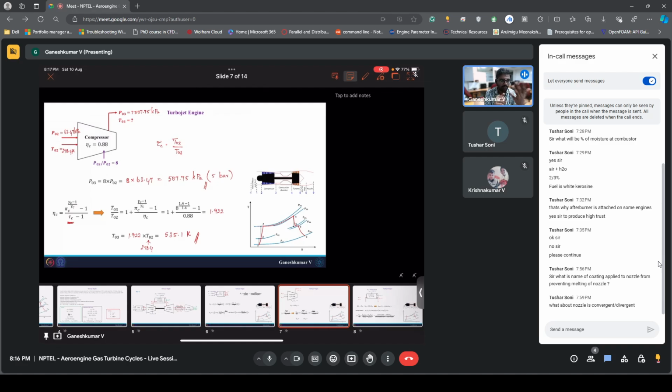But you will learn more reasons to prefer each engine. It's not just the altitude. Okay, I can give you a hint. It is various parameters, for example, your thrust requirements, your specific fuel consumption. All these things will determine which engine to prefer.